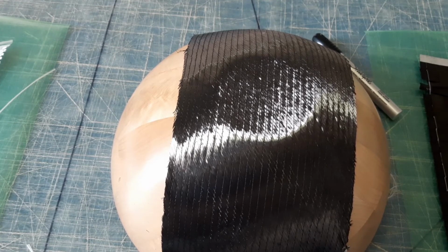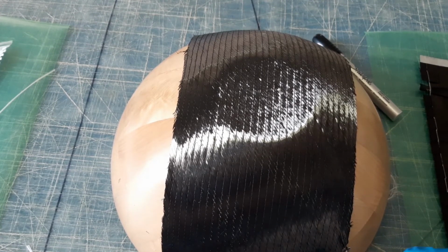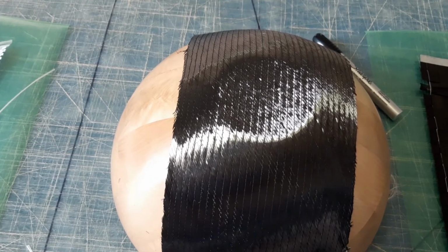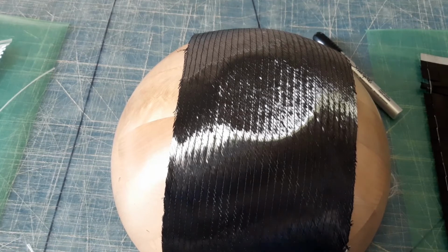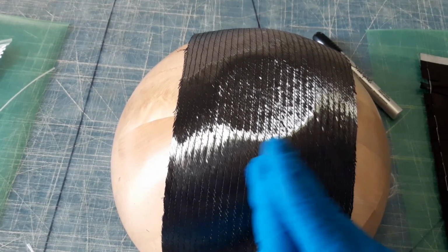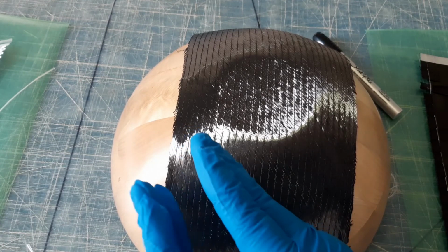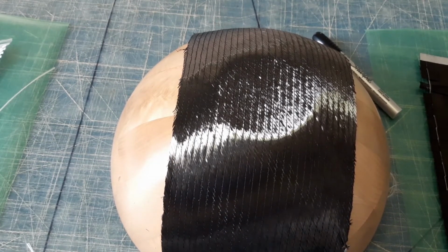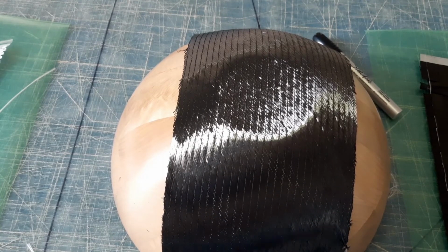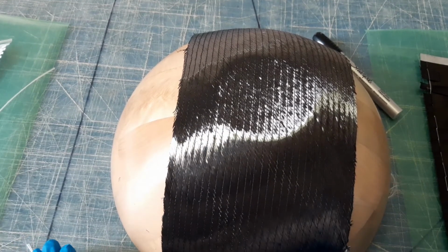If you have, on the other hand, a legacy quad which is 0, 90 and plus minus 45, and these layers are thin, so maybe you have to put first a 0, 90 and then a plus minus 45, then a 0, 90, then plus minus 45. Because for plus minus 45, you'll have to turn the direction of the layup by a certain angle. You will have to coax it in a different manner.